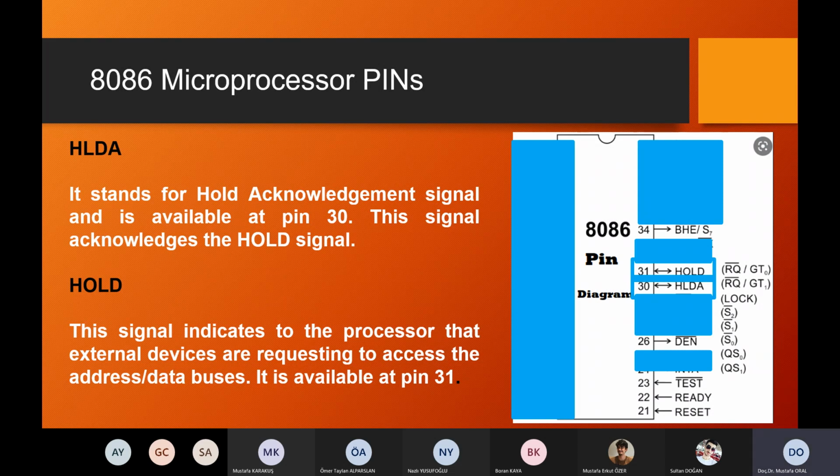When I say stealth mode, if you remember, last week I talked about the three-state, Z state. The stealth mode makes the microprocessor invisible on the lines by taking the outputs and inputs to Z state, the high impedance state.